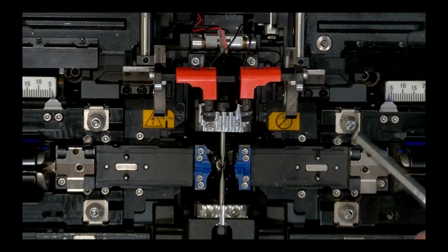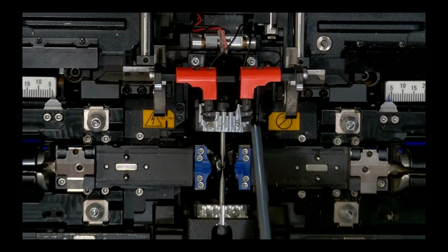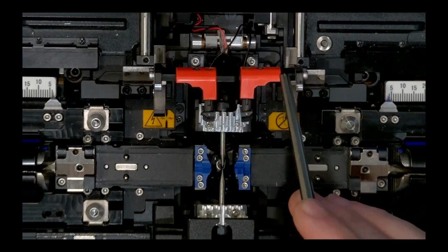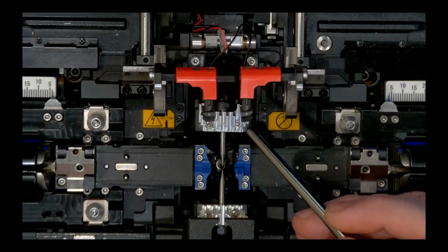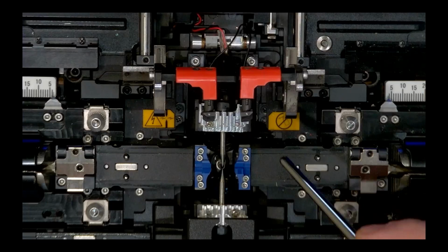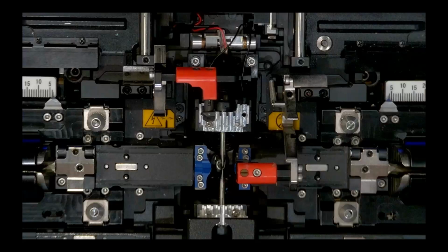These are linked to your wind protector motion. Right now, I have the wind protector all the way open. This is how you would have it if you were cleaning the mirrors, for example. But this allows you to fully see the rear electrode, the rear electrode mounting block, as well as the chip clamp mechanism. You've got your actual clamp here that moves up and down, and this clamp can slide from side to side as well to accommodate different positioning of the V grooves. And you can also manually lower these to verify the position of your fiber, make sure it's going to sit correctly in the V grooves before you close the wind protector.